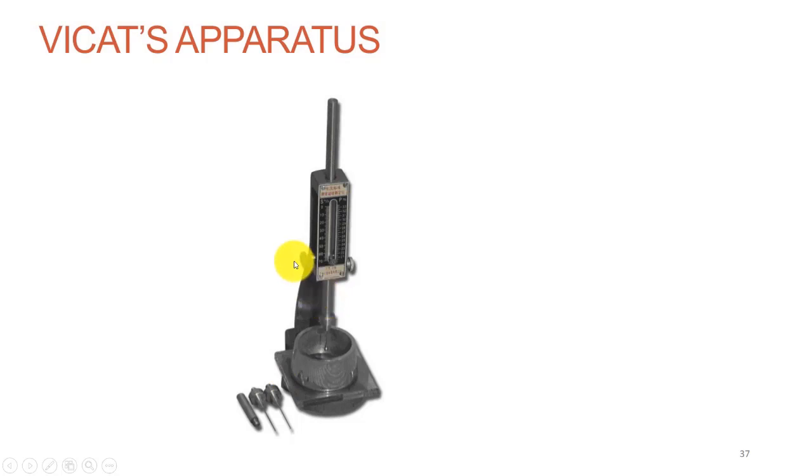For the consistency, you use the plunger. This 10 millimeter plunger you use for testing the consistency of a cement. You add the water content into the cement and determine how much the plunger penetrates into the cement. When it gains 5 millimeters of penetration from the bottom, then you will say that it has attained the desired consistency.